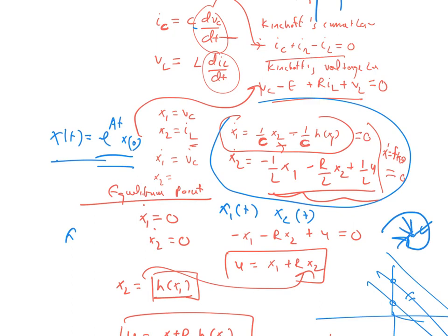If the system is stable, I'm saying that the curve, doesn't matter where you start, goes to the origin. That's one statement I make. Now, how it goes to the origin depends on the eigenvalues of the linearized system, whether I go straight like this or spiral in. Those kinds of behaviors can be studied using the linear analysis.